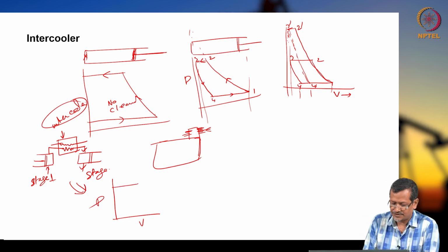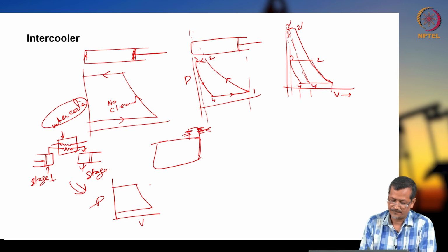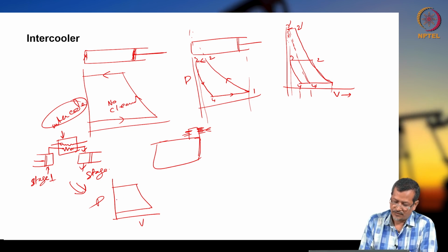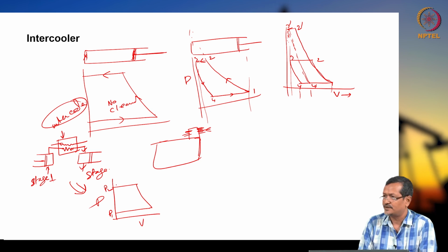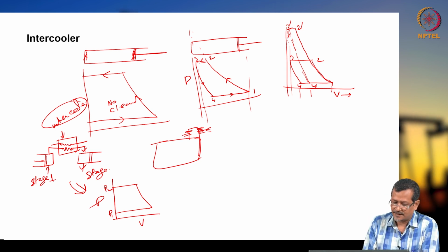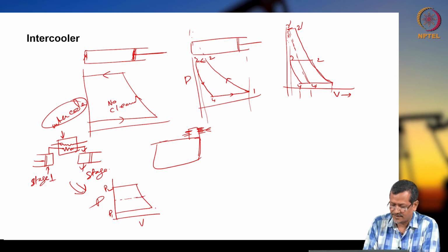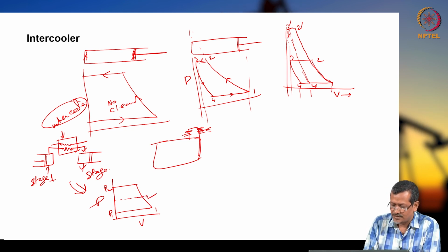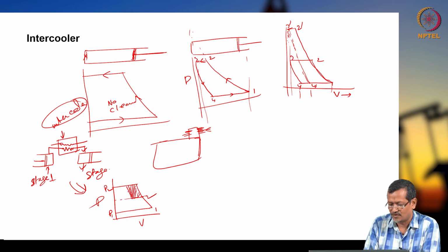So initially the curve will be like this, let us say I do not have any clearance volume initially, assume, okay. Now in single stage this much pressure, P1 to P2, we are raising, but some engineers came and said put one intercooler. Intercooler means after first stage 1, 2 you reduce temperature, this much energy will be saved actually, again compress,